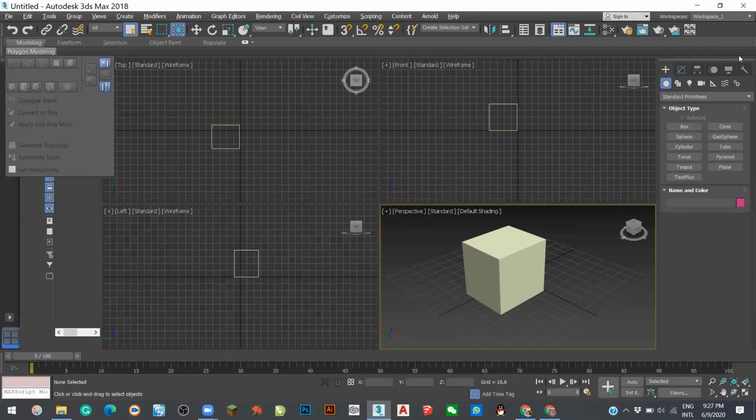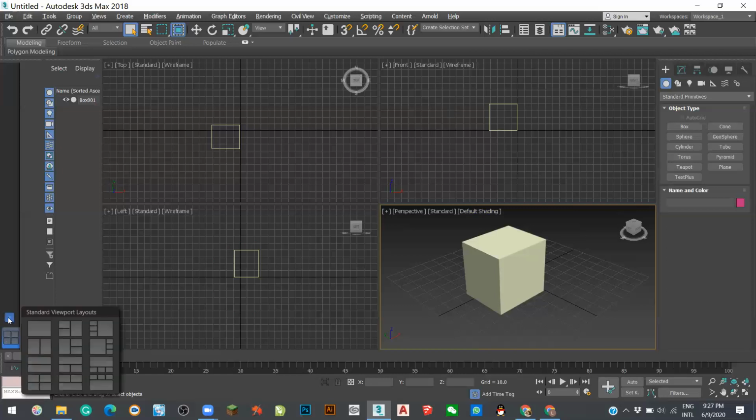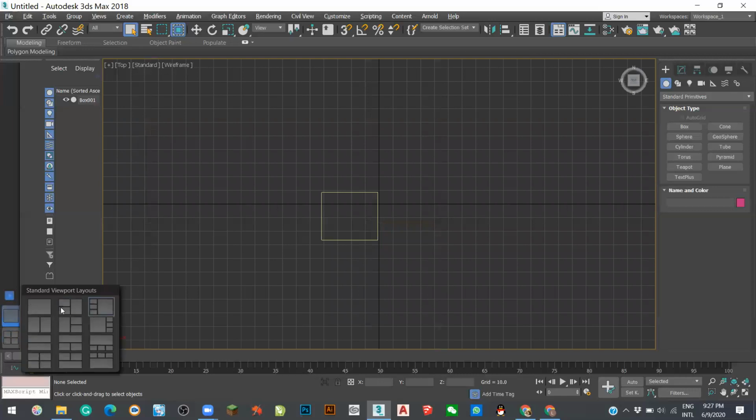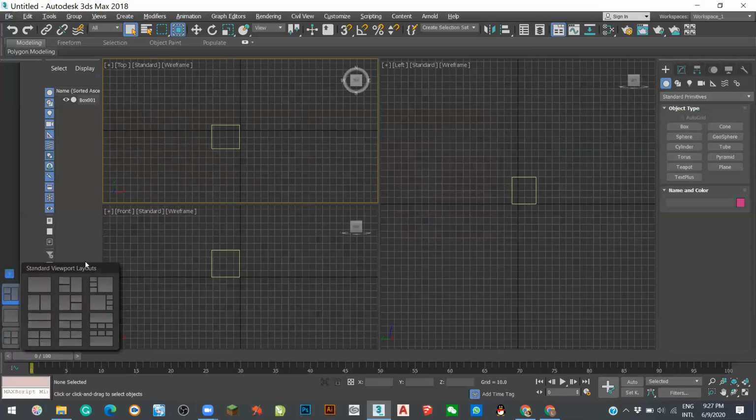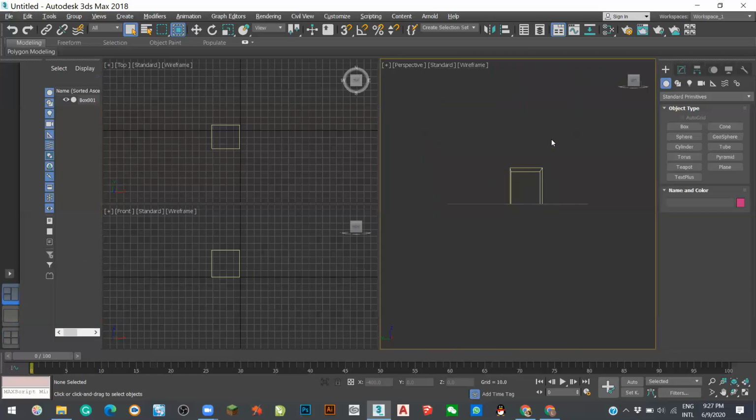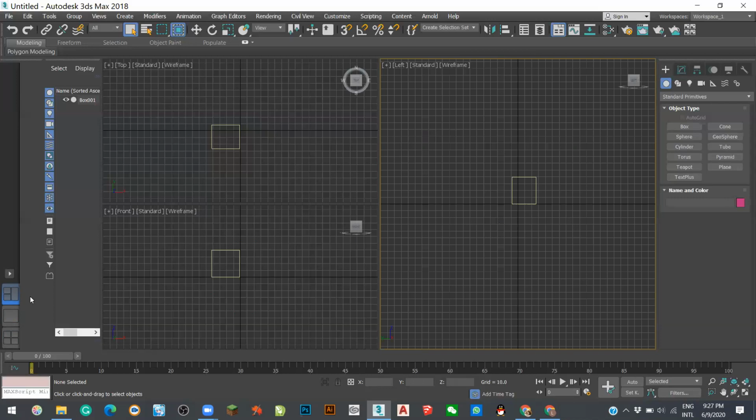And another one is, okay, here you can change your viewport layout. 1, 3. First, this one is left, then I can press P to get 4. I can move the view cube here. Then just use my mouse to roll over, or you can use Alt and your mouse scroll button, move up and down, left and right, something like this. Okay, you can roll over. So this is left. Okay. I can change back to 4 or 2.